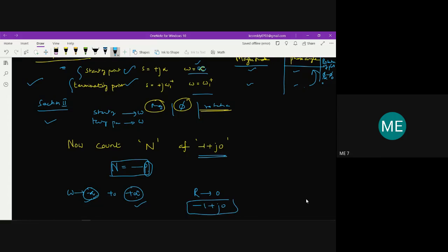The rotation which you are doing here for these omega values will not affect the encirclements of minus 1 plus j0, as these encirclements are almost 0. So it will not encircle minus 1 plus j0, because the plot is going to end at this particular point, the origin. Minus 1 plus j0 will be here, so it will never encircle this minus 1 plus j0.